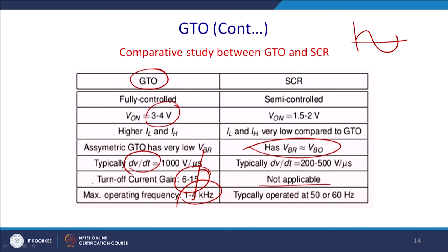And the thyristor is typically operated on a 50 hertz supply and mostly in converter operation, where SCRs are operated for rectification, as you can understand, that is applicable for natural commutation, and it will commute at the normal power frequency of 50 and 60 hertz.